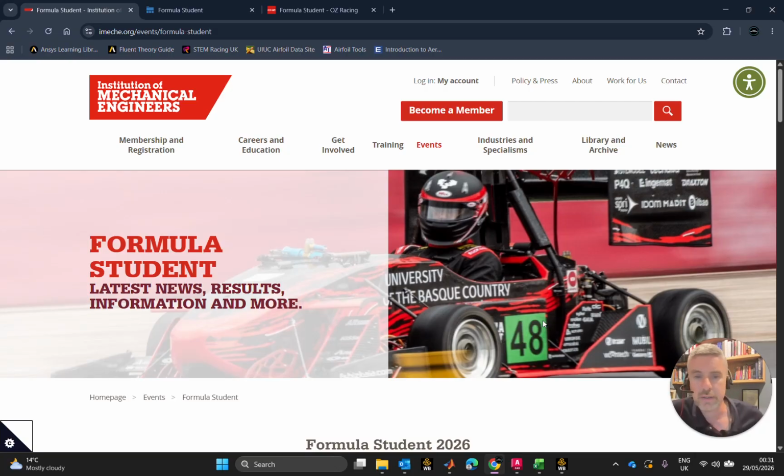But yeah, there are certain aspects of the car that you want to make sure that you have done. Aerodynamics is not really one of them. Obviously, there are more points for aero considerations, but the main name of the game is to get a car on track so that you can race it. You need a chassis, suspension, tires, a steering system, a powertrain, an engine or else an EV, a gearbox, a seat, steering wheel, and so on. Then you can race a car.